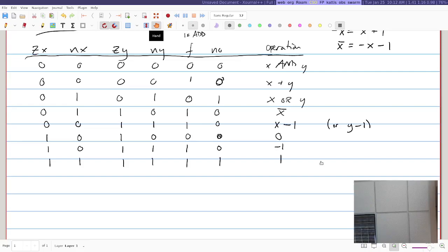But that's not how this works. The code is not looking it up in a table or something. Each of those bits goes to one place and tells something what to do. Literally, if you have some instruction, there are going to be 6 bits in that instruction that it's just going to yank out and send straight to the ALU, and the ALU will just do what those bits mean to do.